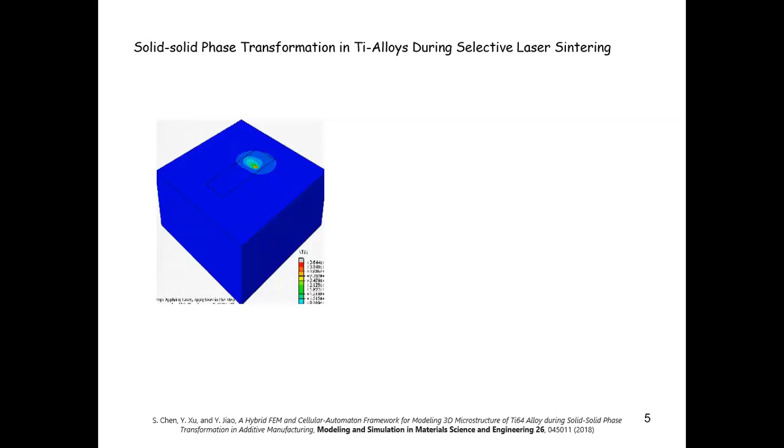So this is a more detailed view of this particular laser sintering process. I think it's just cool to give you some idea of the most current processing technology that we have developed. Again, this is showing the simulation of the temperature field as you move the laser spot around the system. Here we're just trying to sinter a rectangular plate from the powder pack. The reason we do this is because it's easy to implement in the simulation, but in principle, you can actually do much more complex shapes.